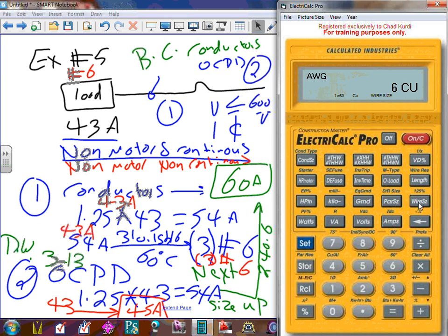Okay, now I'm going to use the same example just to give you an idea. If we're going to put this feeder in Arizona at 50 degrees Celsius, right outside, we're going to size. We're always going to start with a load. Always. And I'm going to size a cable, and we're going to put my cable in 50 degrees. The only thing that's going to change is the cable, because the overcurrent protection device, guys, is going to be sitting inside.